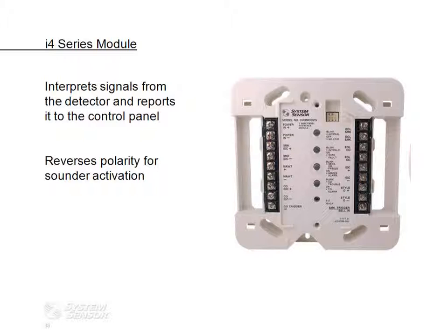And then also for Style D, the module allows you in 2-wire systems to wire Style D, sometimes known as Class A, and that's where you can home run the wiring back from the last detector to the module. That's not all it does. There are some other questions in here that were asked, and they'll touch on other aspects of the module.